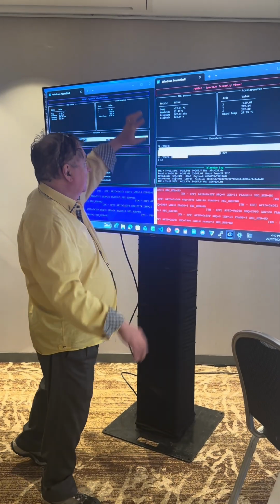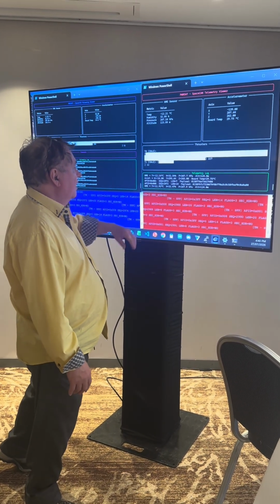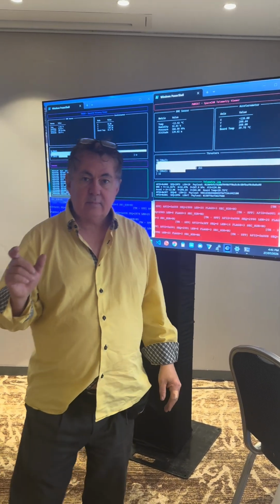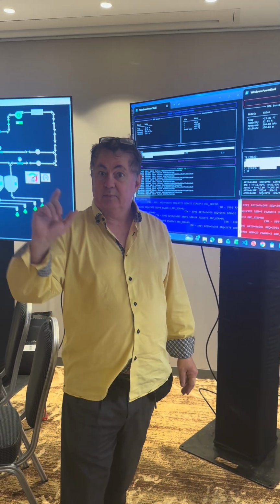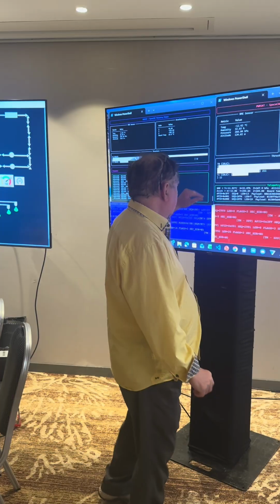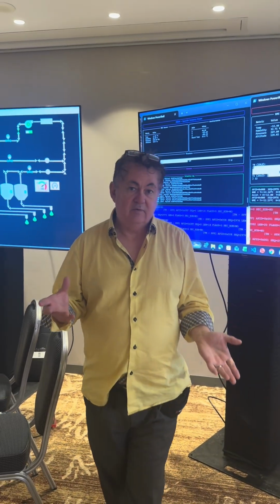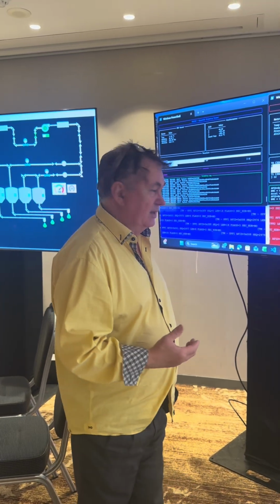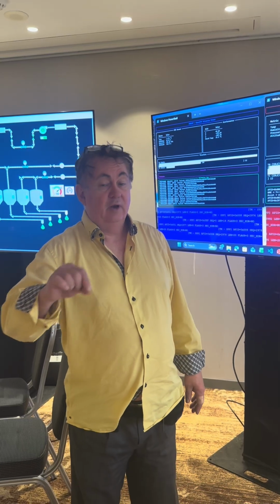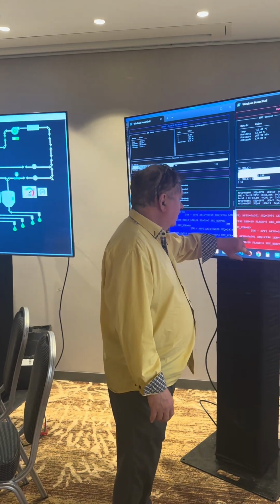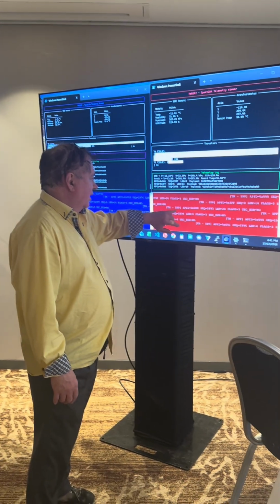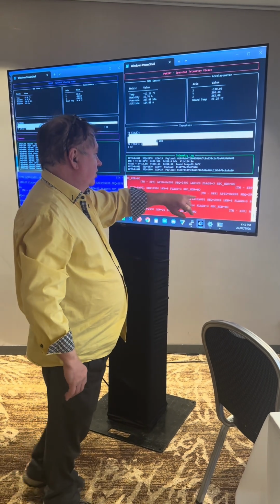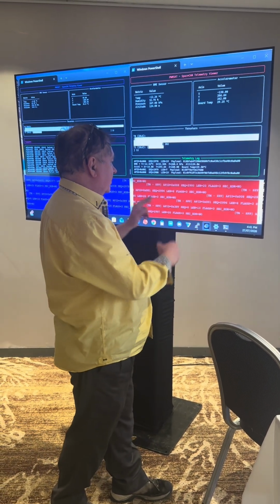When you talk to a bus to get information on your sensors, you need to address the bus with your APID, which is like a command that you send. And commands like ping is APID 1. In this case, you can program them to whatever you want, depending on your mission design, your payload. And what you find is, not unlike TCP, you have a packet type, APID command, a sequence, a length, a payload, and then your flags and the sequence too.